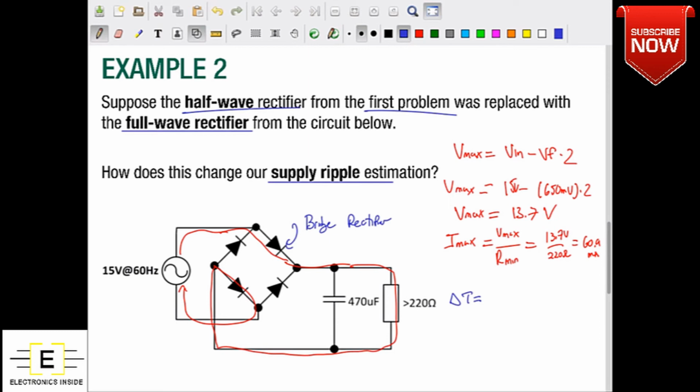And that means that the total time from discharge to that charge start again, instead of having this shape, right, where we had a DC pulse and then half the time off, we now have a DC pulse followed by a DC pulse. So the total discharge time, the total cycle length, has been halved. So instead of using a discharge time of 16 2/3 milliseconds, we're actually going to use 8 1/3 milliseconds, which is half of that.